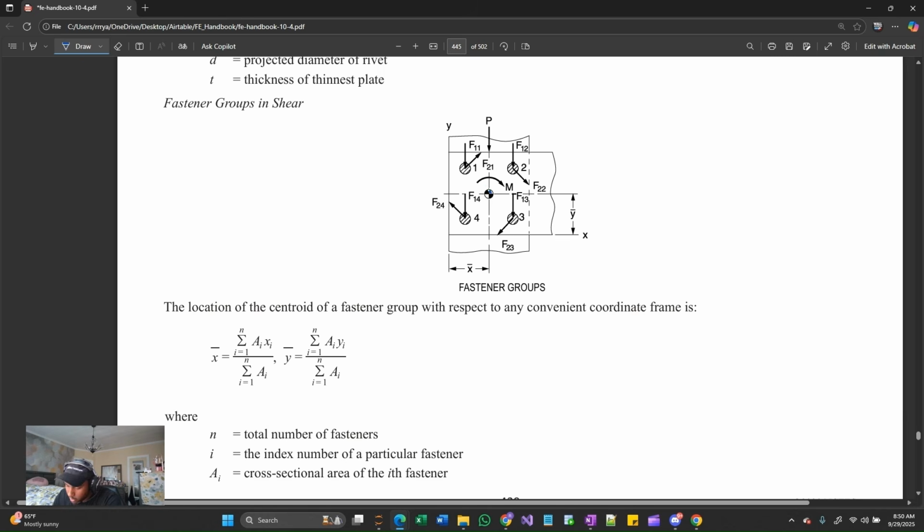One of the hardest parts about these kinds of problems is really picturing that secondary shear. All we do is connect a line from the centroid to the bolt of interest and just draw perpendicularly, aligned with the direction of the concentrated moment, the secondary shearing force, and that's an important concept to remember. So it could come from eccentricity or it could be just applied on the bolt group. And that's how we determine the secondary shear. And the first part of the problem was really determining the location of the bolt group centroid. And it just came from statics, when we were finding the centroid of different shapes, pretty similar to how we find the centroid of the bolt groups.